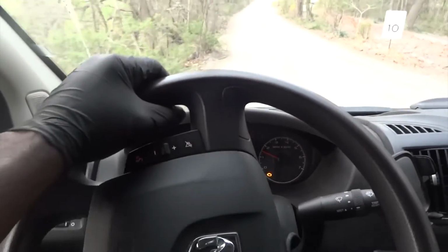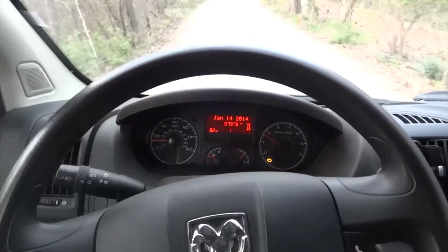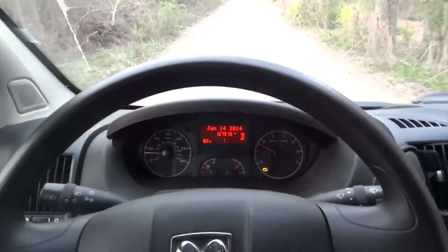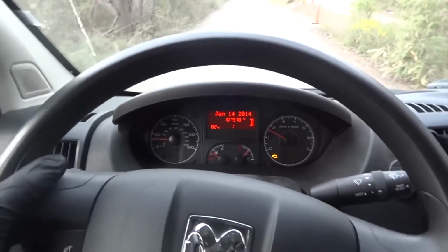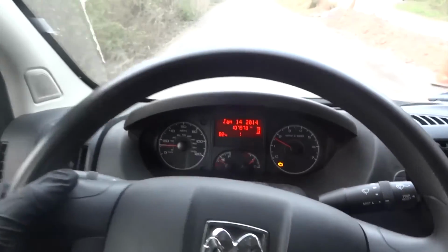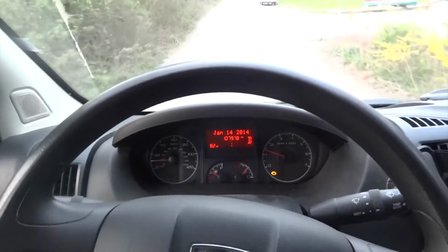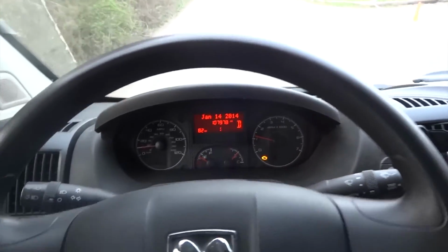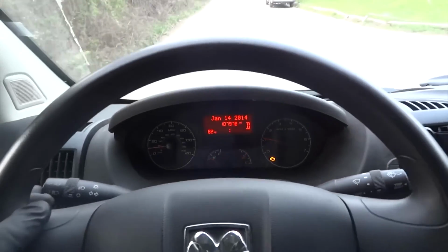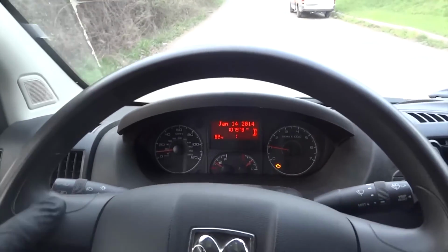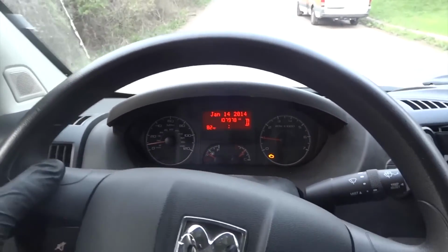I said that I was gonna use my RTL tool to open the EGR valve to see if our engine RPM is going to change at idle when we open the valve. After opening the valve, if the engine RPM doesn't change, that can be an indication of a defective valve or a clogged passage in the EGR system.